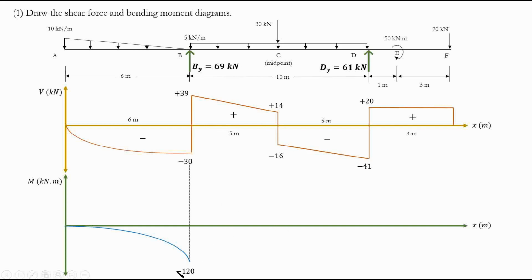So we'll add that value to negative 120, right? That value was positive 132.5. So negative 120 plus 132.5 is going to be positive 12.5. Now, of course, how do we know that the change is positive or negative? It's obvious, right? The area under the shear diagram is positive. And that's why we say negative 120 plus 132.5 gives us this value.